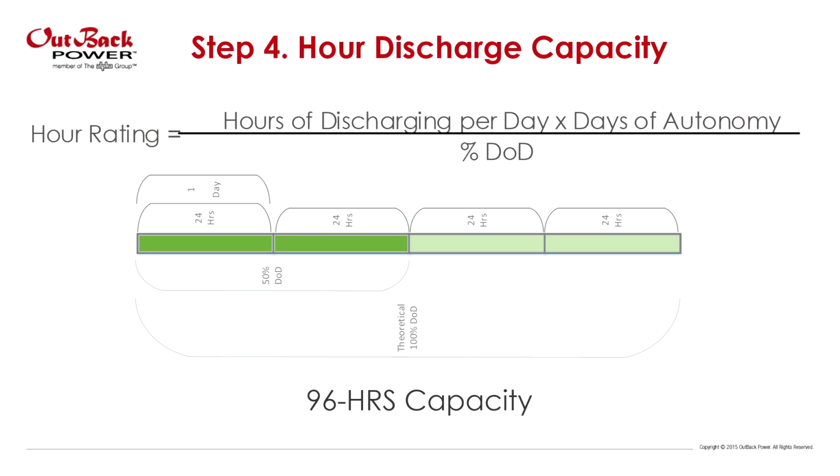So here we have our battery sizing, okay? We have our hours discharged per day times days of autonomy divided by percent discharge per day. So this is our depth of discharge. So here we have our battery bank, okay?